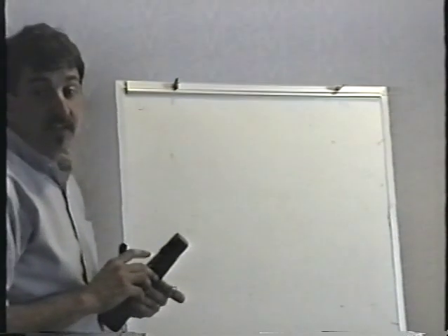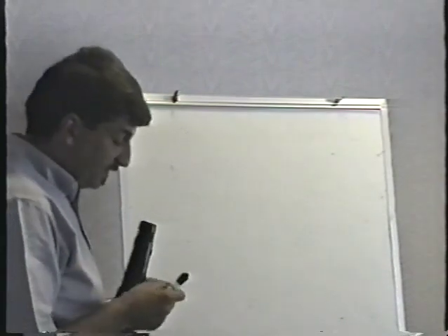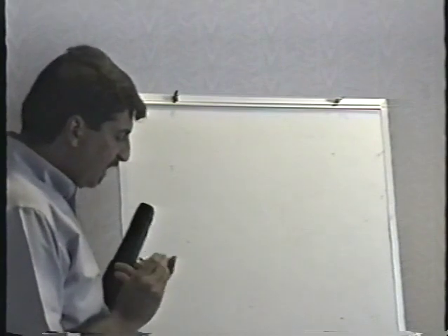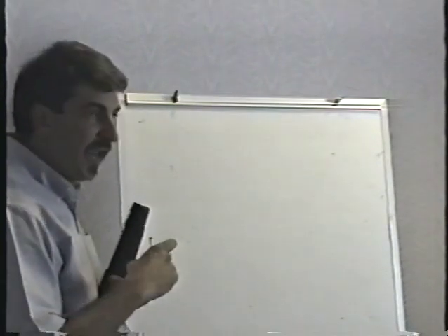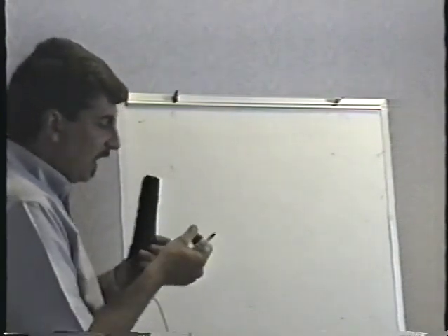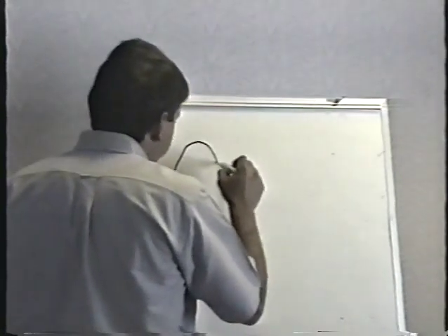In order to test the transistor, you do have to know which lead is which. You have to know which lead is the emitter, which lead is the base, and which lead is the collector. If you look at the TO3 package that I gave you, that's the big one, you see that there aren't but two leads sticking out of this thing.